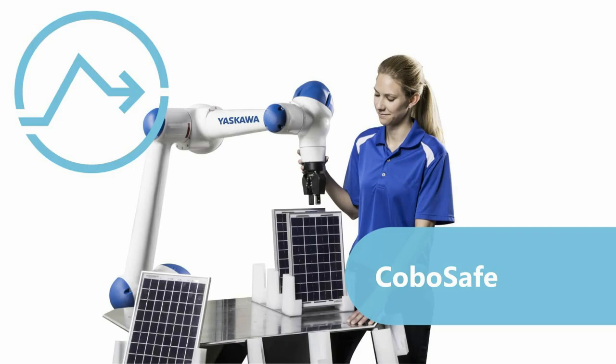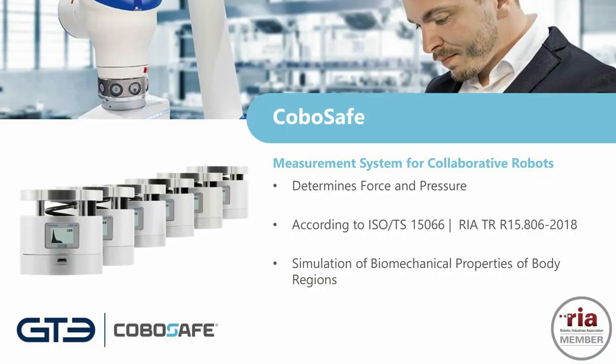Of course, the CoboSafe system is able to determine force and pressure according to the currently most important standards like the 15066 or 15806. And like I mentioned on my first slides, CoboSafe is able to simulate the human body compression behavior as realistically as possible.